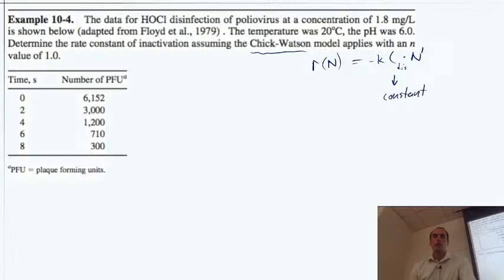So within the context of a disinfection chamber, that's often going to be true, or we're often going to be aiming to achieve that. Maybe something like ozone that decays a bit faster, perhaps we are bubbling it and injecting it into the chamber throughout the system to maintain a relatively constant value of it. At any rate, that means that we can put K times this C for the disinfectant, both as a constant and just simply call it K star, and then it looks very much like any of the other stuff we've encountered.